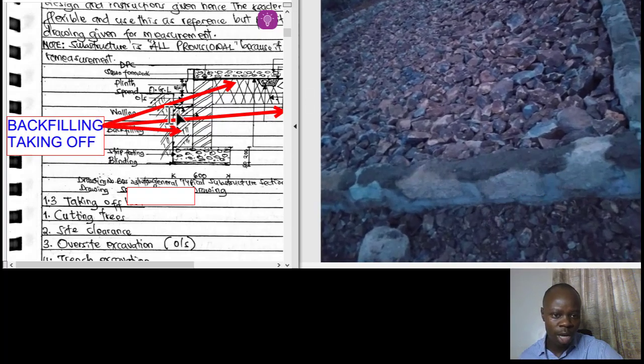Okay, this is where the wall is, and the wall is here. And then now the external sides of the foundations, we are concerned about the part where we have the trench. So you remember we did the trench of say 2 feet or 600 millimeters, if you could say so. Then now to the external side of it is where we are going to do the backfilling. So we need to do it in cubic meters, and for cubic meters we need 3 dimensions.